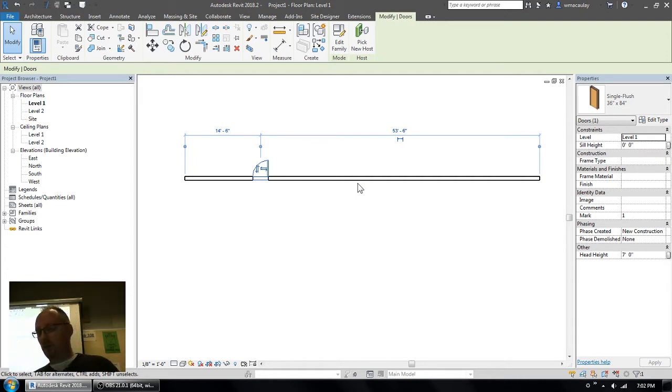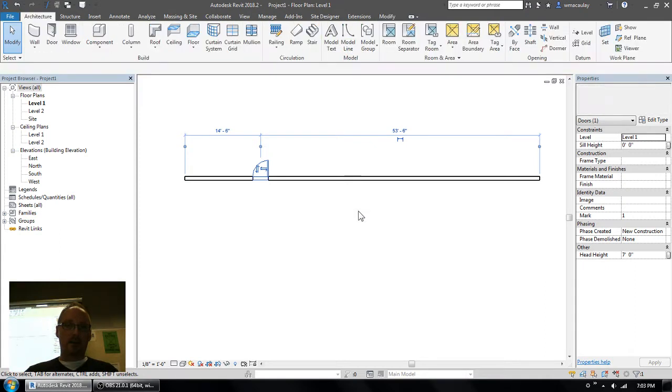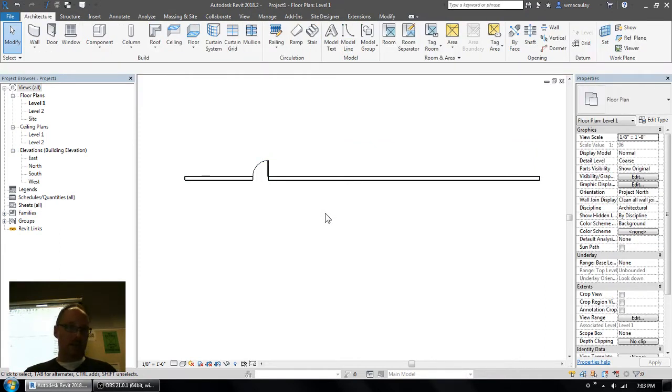Looking at our notes here, the third item on the top of the page there is in-place families. So you've got your system families, which are the basic building blocks of your projects. You've got the component families, 2D and 3D, which are loaded into your projects and used as needed. In-place families, we'll go over that in the advanced course. That is where you do in situ modeling of some one-off geometry like a custom fireplace or some other component of your project that is a standalone design item in your project. So let's get into the family building process here.